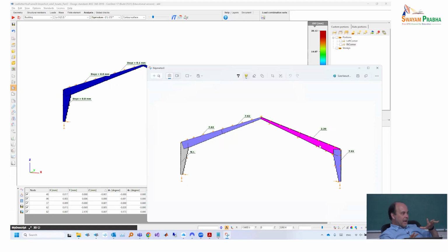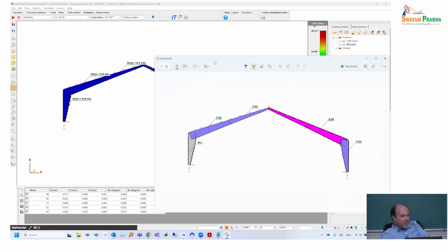It gives you a certain feeling that at least at the end of the day, there is no member which has got nothing. But it's not very relevant. So if you are really willing to go into this, it's always better to just select that one relevant combination and limit this game to that. Now here the results are more understandable. So they all refer to load combination 3, which might not be the relevant combination for every member design. But if we just limit our game now to load combination 3, then for the whole rafter, regardless of the fact that I made it from 2 members, 2.2 was recommended, which is this mode.